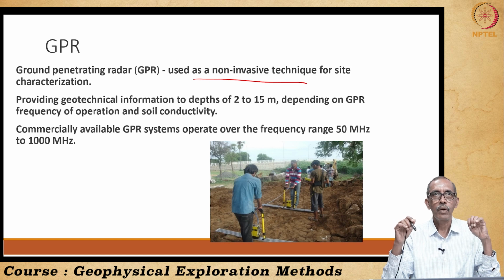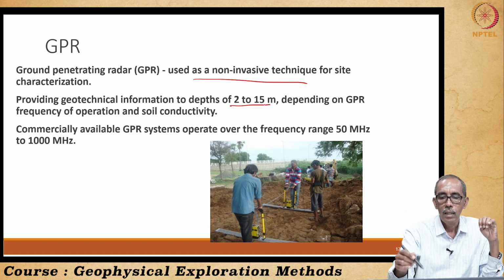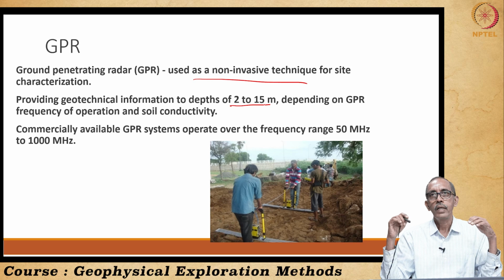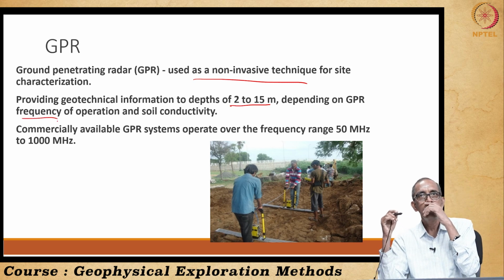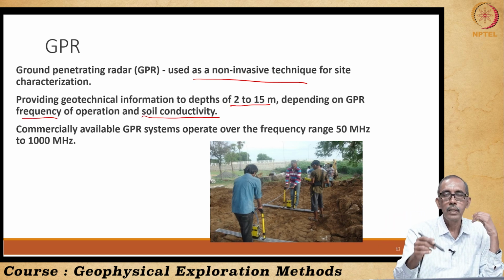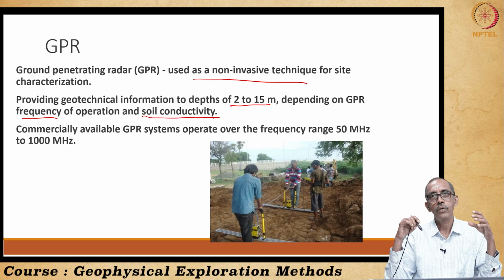It provides information up to 12 to 15 meters, sometimes up to 30 meters maximum, depending upon the frequency of the antenna which we use, as well as the property of the soil, right. Especially if you have completely wet clay, then these radar waves won't be able to penetrate, right. Only up to a few meters we will be able to understand.